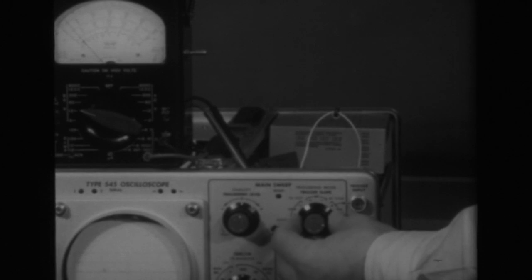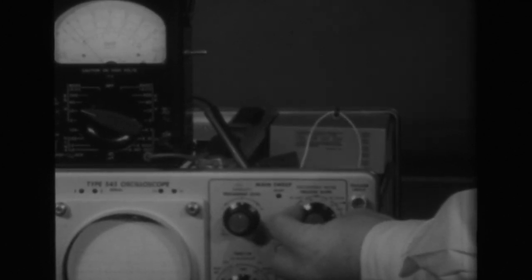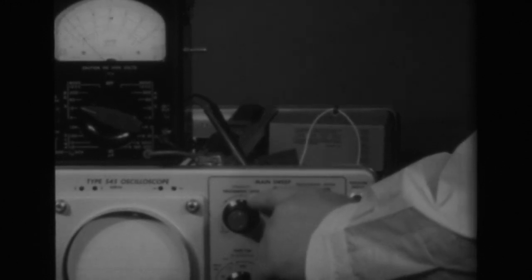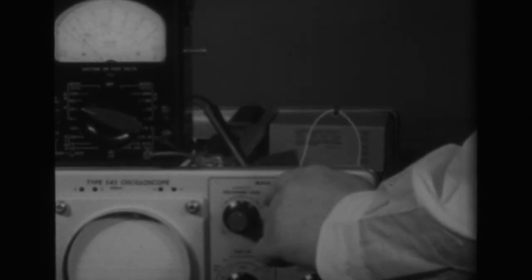Now verify again that changing the slope selector switch from plus to minus external slope still causes the meter to stand perfectly still at about 1 volt. That shows that we have adjusted the triggering level control correctly. Now notice whether or not the white dot on the triggering level control stands exactly opposite the engraved 0 on the front panel.